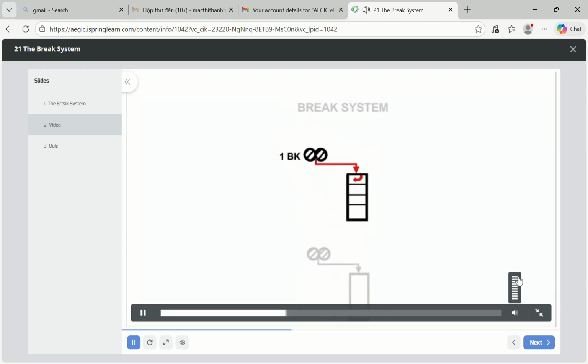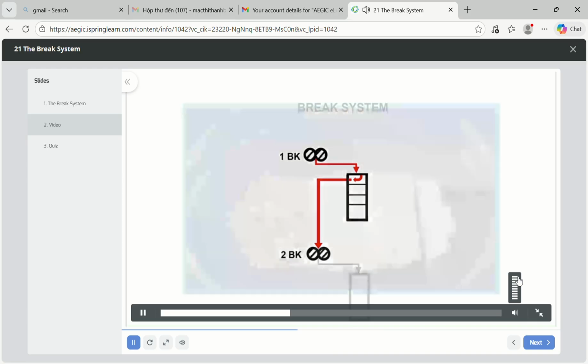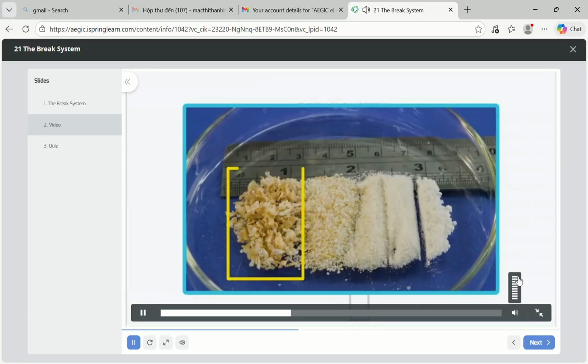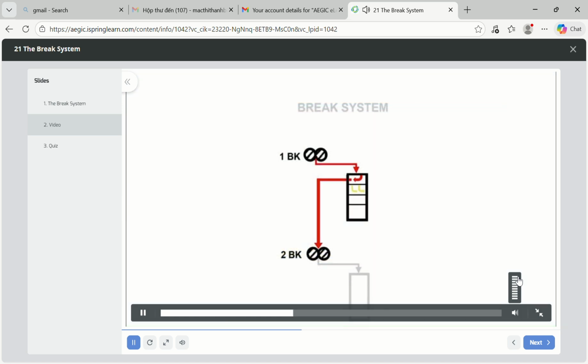The stock passes over the coarsest screen first. The large branny material overtails to the next roll in the break system called second break. The removal of large branny stock like this is called scalping. The remainder of the stock is released through the screen for further sieving through finer screens.